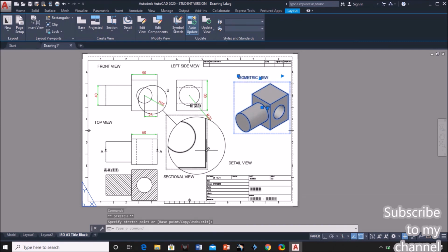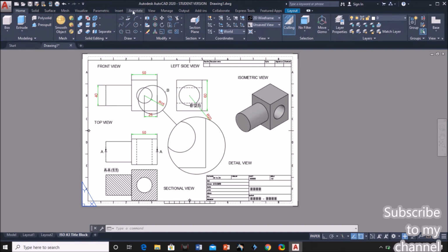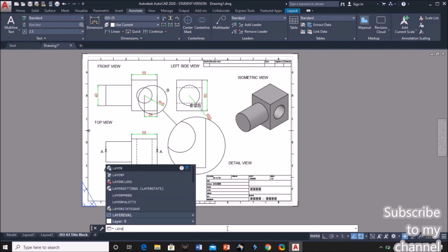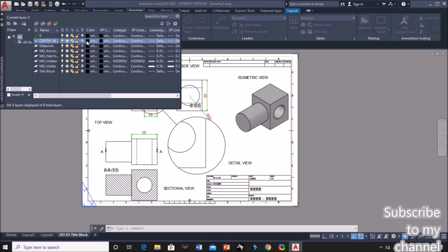So after that, now I need to change this text into one layer. Coming to layers, click on the layer option, the layer command. The command for layer is layer. Enter. You will get different types of layers. I am creating 2 layers, that is center mark, and I'm assigning the color for the center mark as green.